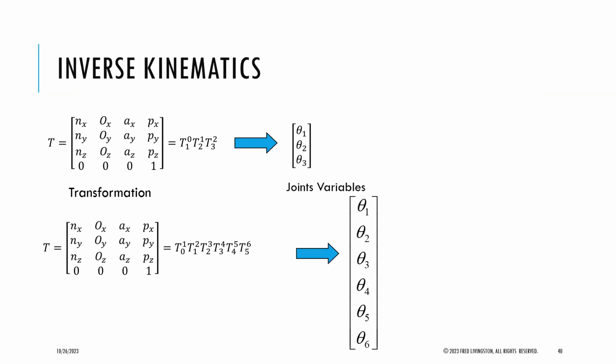I'm still at the same position, and so I have 2 different Q1 and Q2 to give me things here. But the pose might be slightly different. So you also need to check and make sure there's a valid solution there. And eventually you want to do collision avoidance. You want to make sure your arm is not trying to go through a wall to pick up an object or something like that as well.